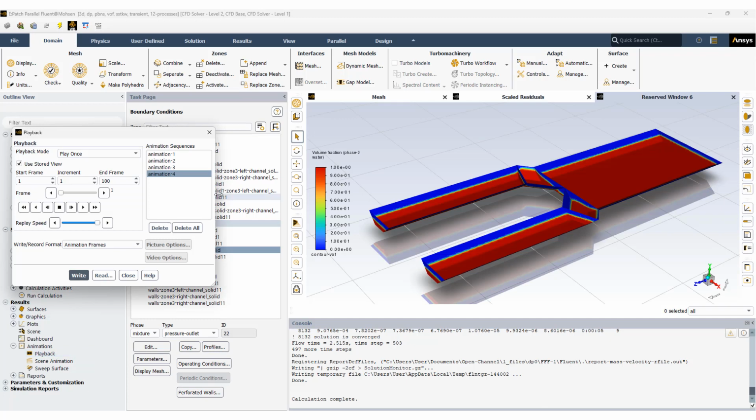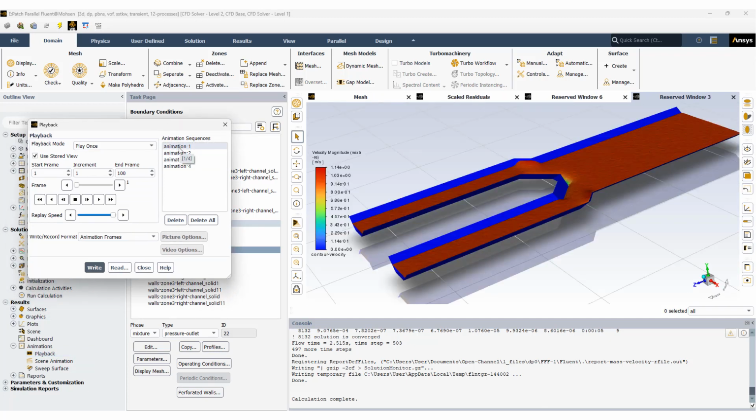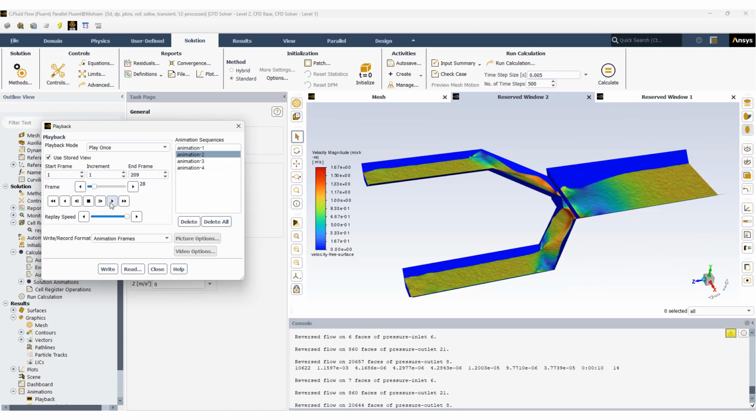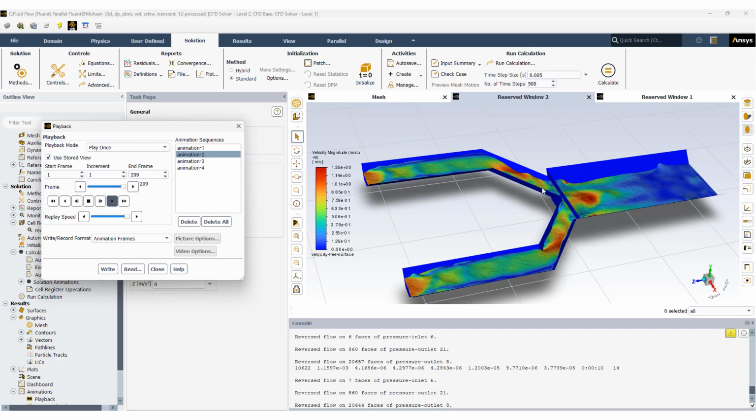Let's compare the simulations, compare the animations to see what's going on here. Again, these are the velocity contours at the free surface, and now remember what we had before. For this one I will play it again. You see that the water here is converging together, and the delivery from these two branches comes back at the sides and affects the flow in each branch. So from the outlet toward the inlet, even getting to the inlet, the waves come back in the opposite direction.